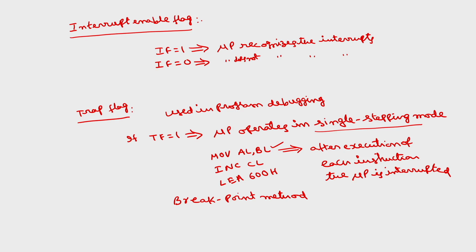This is the third operation we are discussing, the internal data operations. So, the first one stores the 8 bit of the data, for which we need various registers. Second one, it will perform the arithmetic logical operations, we need a single ALU. Then the third one is testing for the conditions. So, in testing for conditions, the microprocessor needs a hardware element called flag register. So, I have discussed about 8086 different flags. Then the fourth internal data operation is to sequence the execution of the instructions.